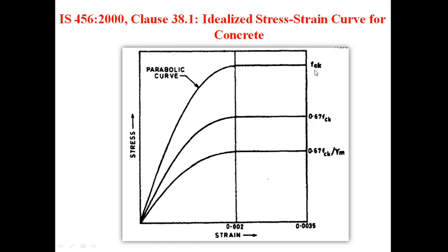And this is FCK, the characteristic compressive strength of a 150 mm by 150 mm by 150 mm concrete cube after 28 days of curing.